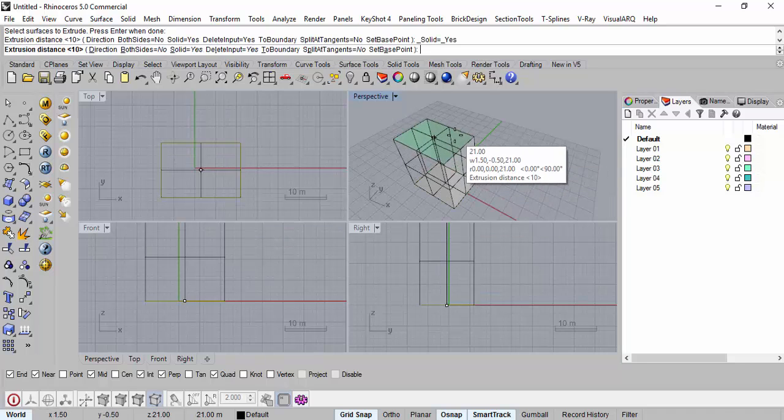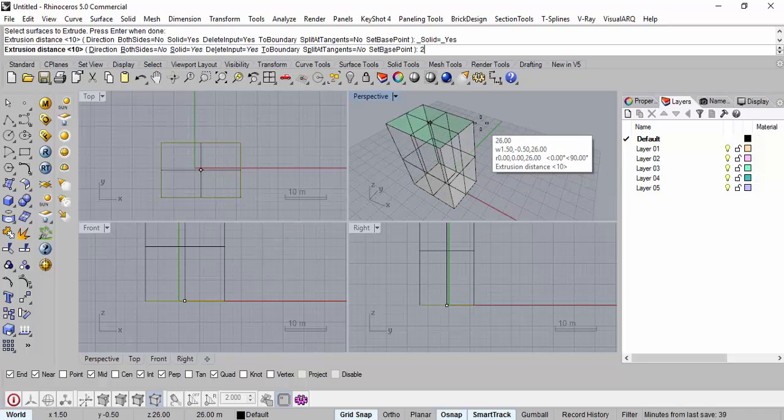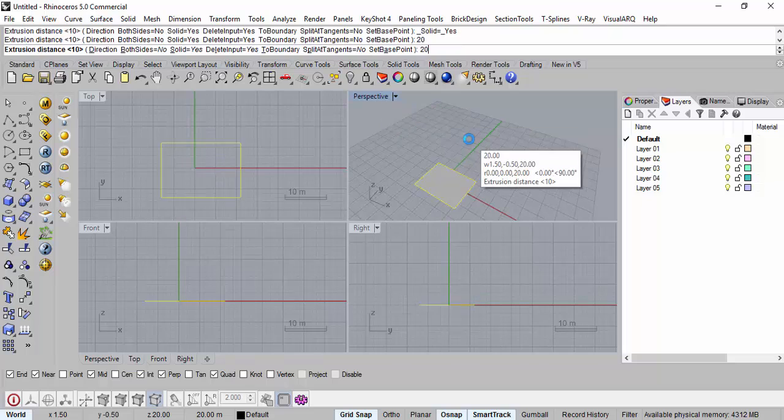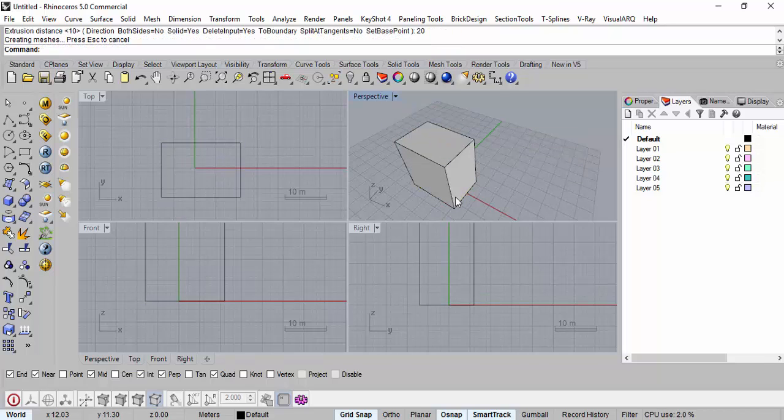Select it and extrude this out. You can give it a dimension. You can just type something, it will directly take it on top here. Just say enter. Fine. Yeah, so we are working in meters here, correct. If it is in millimeters, maybe if you want 20 meters, you will type 20000. Okay, is this clear?